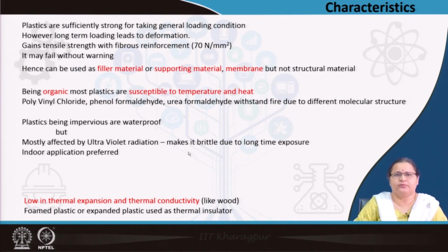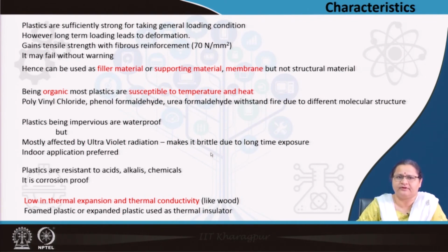Then plastics being impervious or waterproof, but mostly affected by ultraviolet radiation. Hence, it is preferred that it has indoor applications more, because keeping it exposed to ultraviolet radiation makes it brittle and it may fail further without any warning. So, life of the plastic becomes shortened. Yes, you can recycle it if it is a thermoplast, but indoor applications are preferred.